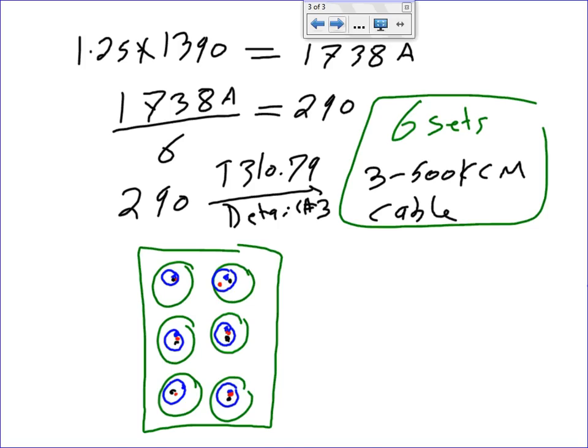You know, that duct bank that I've had to install, and this is usually what's done: you have rigid conduits encased in red concrete. That's the guide, because that way if anything hits it and they see that it's red, it's a warning sign. And then tracer wires and also a single conductor or multi-conductor cable and a single pipe encased in concrete. I haven't seen much of the same stuff. None of the stuff is like that.